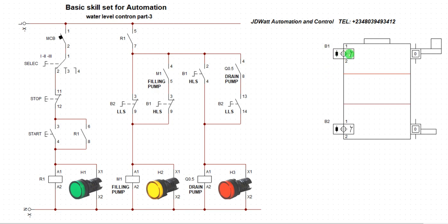So when you start filling the water here and the water gets to this level, this one will get activated, but the water keeps coming. Water keeps pumping. When you get to this maximum set point, it will trip off. It will shut down this valve, so as not to pump in. It will now activate this one to drain out. This one will start draining.